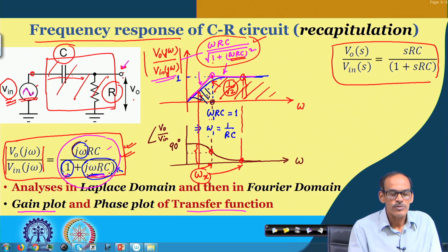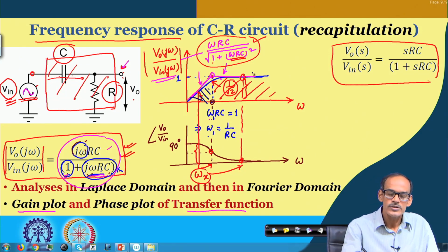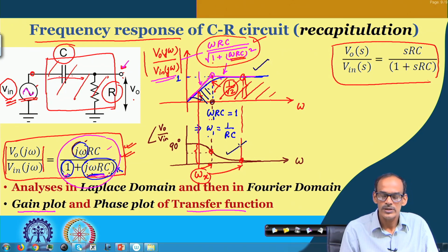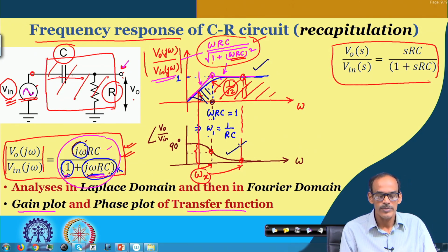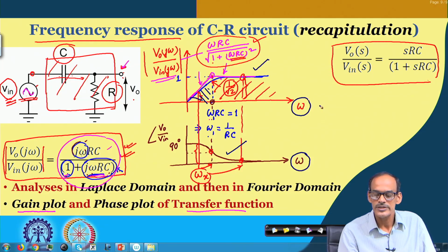So, whenever we are talking about, as I said, the frequency responses, basically we want to see how the circuit behavior changes with the frequency of the stimulus. Now, these two plots, as I said, store the information of the behavior. Typically, instead of considering these two plots, the commonly used plot is something called the Bode plot, where this omega, the frequency, is in log scale,